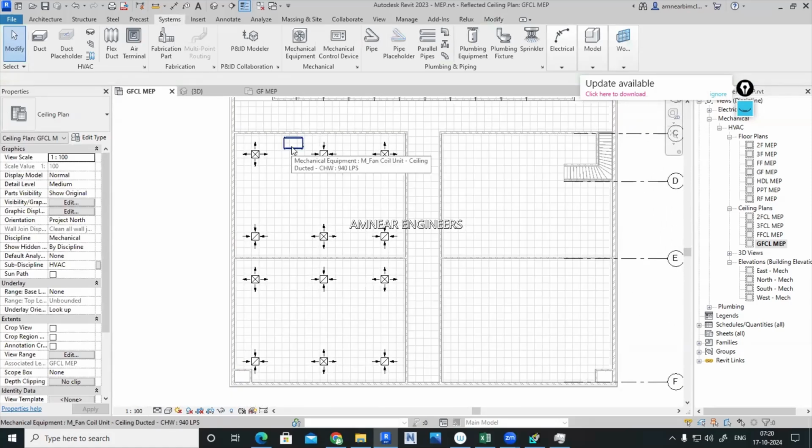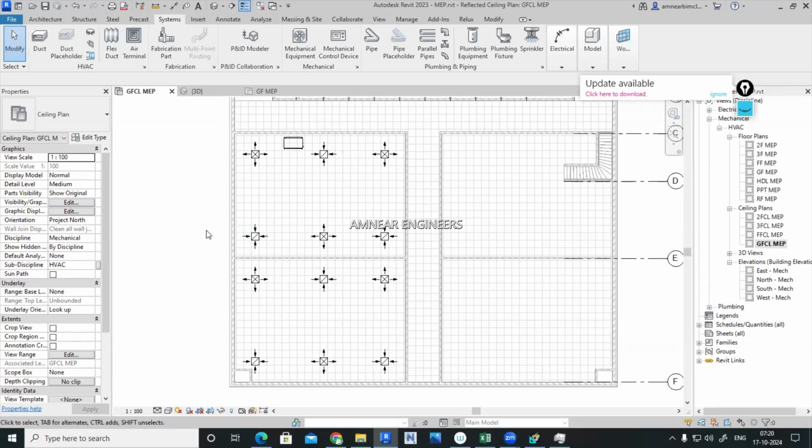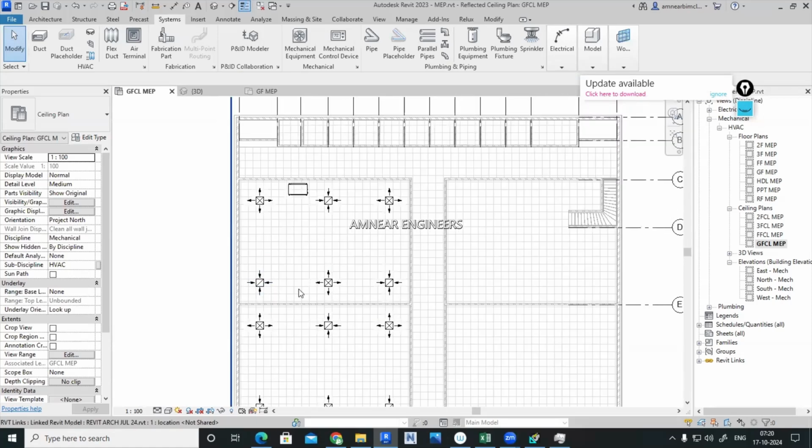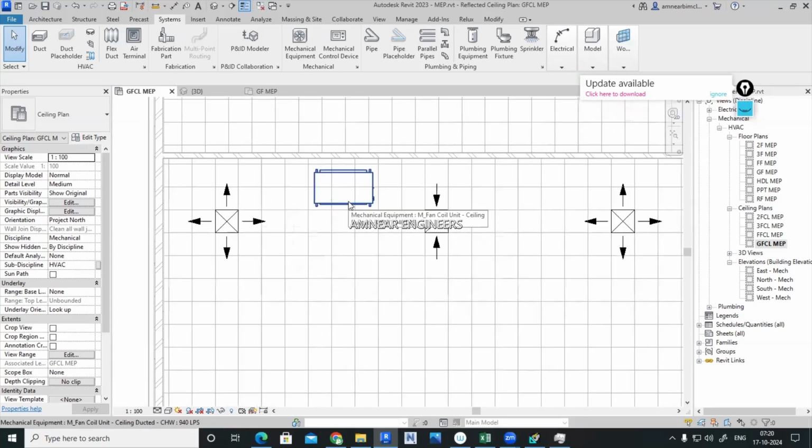And with the help of a single machine, if I am planning to provide airflow rate in two different spaces, I need a VAV box there. VAV box. So a bypass type VAV also I'll be proposing in between. Fine. Okay. See, we can do the modeling now. Duct sizing also, it is possible that we can adjust later.